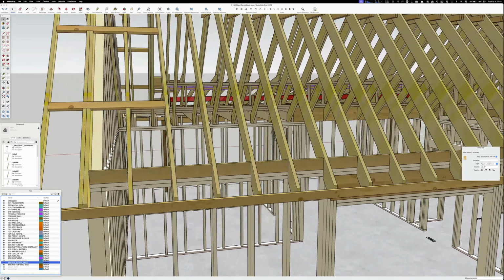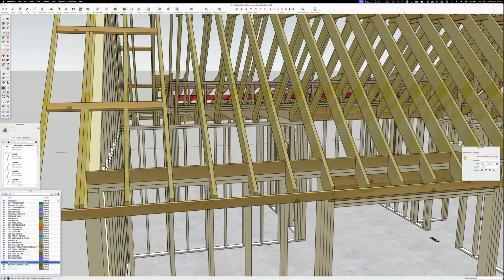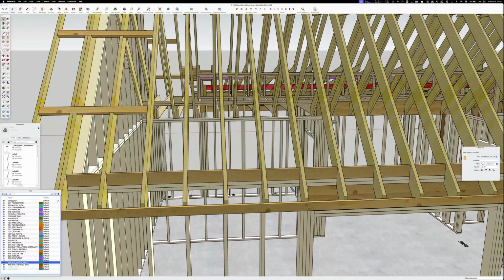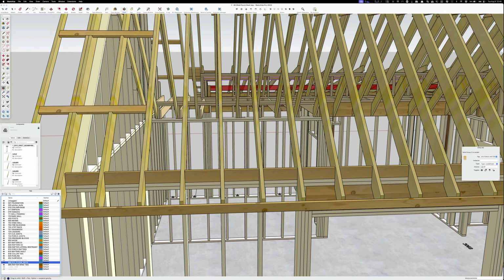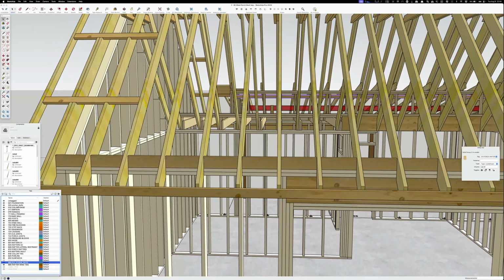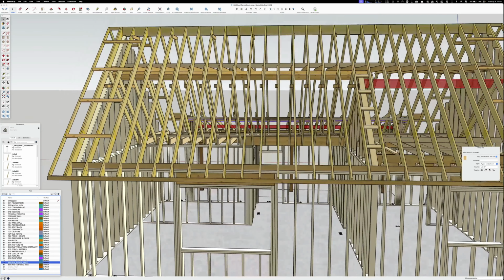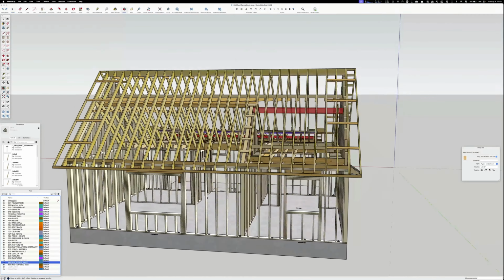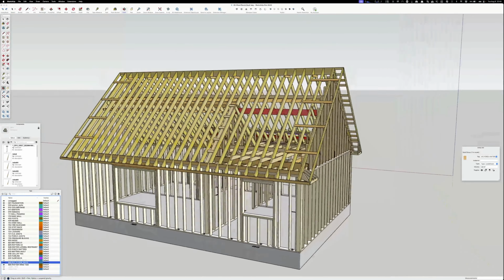When I was in Texas, we never really did lateral restraint, but up here in Washington, they do lateral restraint blocking, and they don't close soffit. So they drill holes in here, and they call them bird blocks. But this is pretty awesome because it keeps the rafter from wanting to twist. I don't know if that's a big deal where you're at, but it is where we're at.